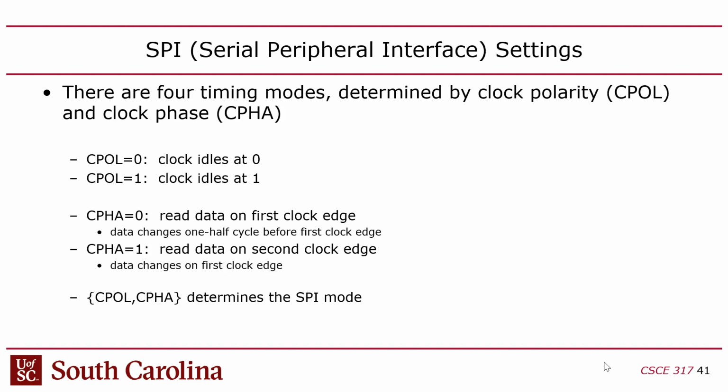Now you might say, well, isn't this a little pedantic? I mean, why does it matter that much? Well, this basically determines how the channel is synchronized and how you know when to drive data on the channel and when the other side is clocking data on the channel, right? So, like I said, if you're wrong about these settings, generally you won't be able to communicate, and it'll usually be because all the bytes that you transact will be offset by 1 bit, essentially. Okay.